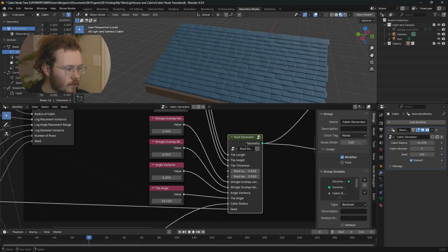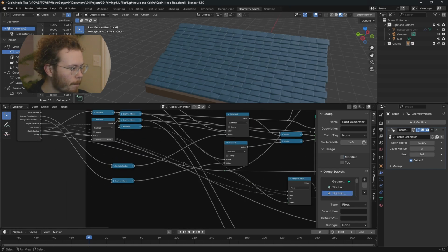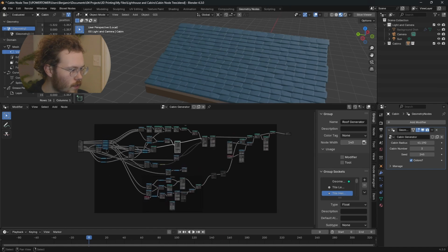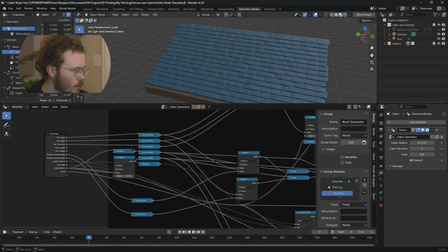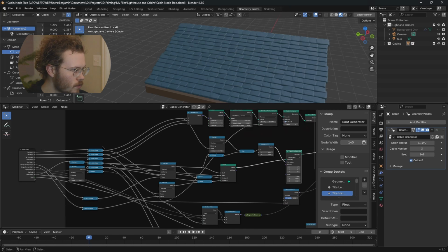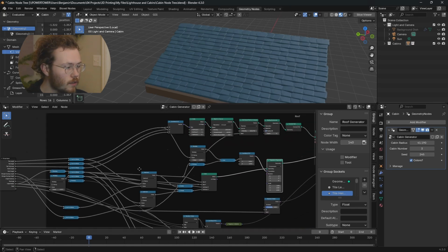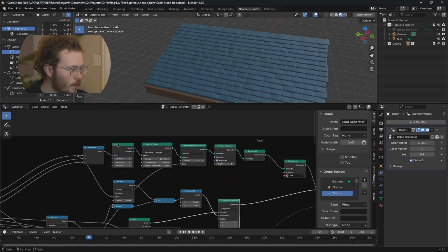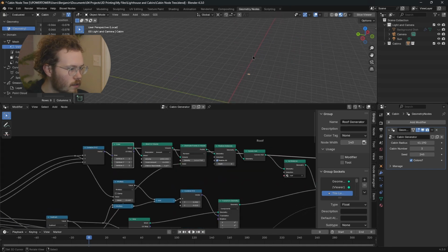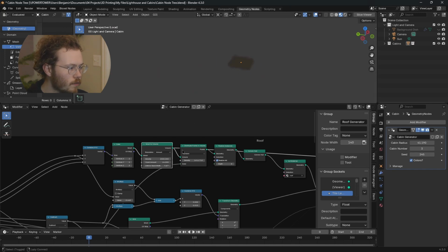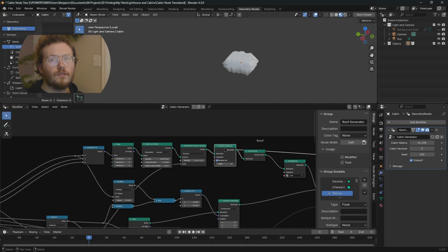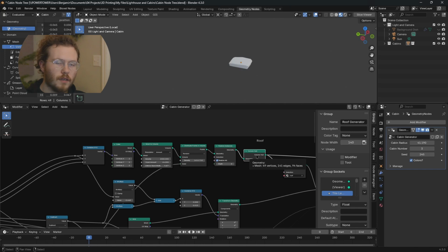So let's dive into this node group. This one is kind of another large one, but primarily what it's doing is it's taking all those values, converting them into metric units, and then up here we're generating the actual tile. So here we go. We've got one individual tile, and what we're going to do is a mesh to volume and then distribute points on that volume using the seed value for noise. We're going to realize those instances so that they're treated as a group, not as individuals when they're brought into this next one, which is convex hull.